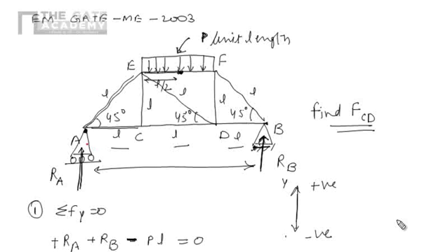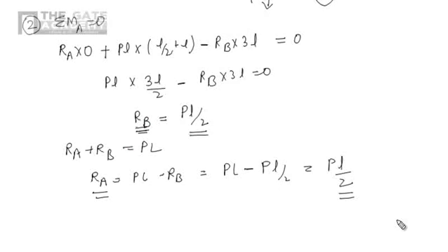So there are two ways. If the loading is symmetric, then we can take the total load and divide it by 2, and we can say that the reaction at the two supports will be the same. It is nothing but the total loading divided by 2. Or by applying the conditions of equilibrium, we can get these values. So we got these values by this way.